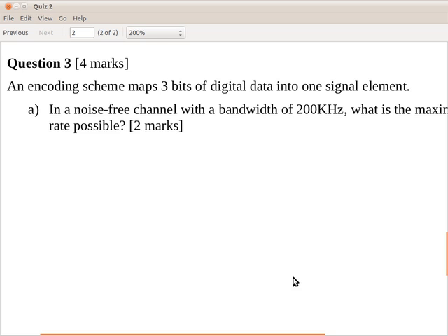So to transmit these 3 bits, I would send at the signal level corresponding to here. If we're using discrete digital pulses, then these may be some voltage level, whatever, +5, +4 volts, +3 volts. Doesn't matter the absolute values. -3, -4. That is, each combination of 3 bits corresponds to one signal element, one level of the signal. With 8 levels, M equals 8.